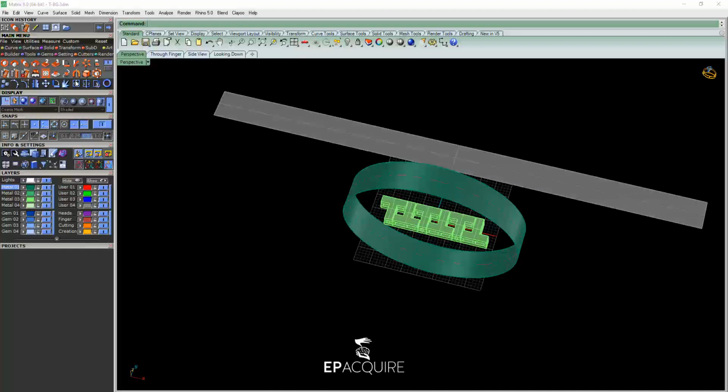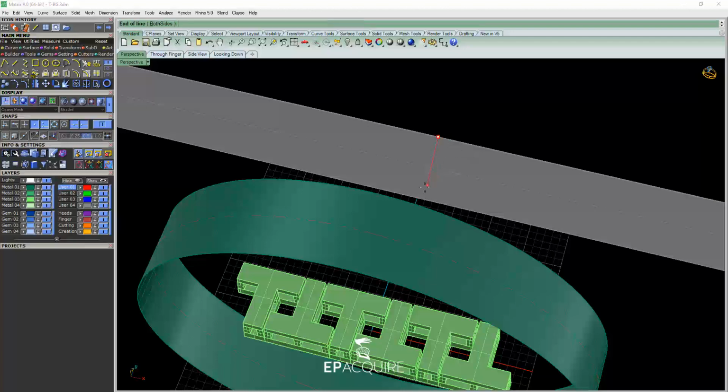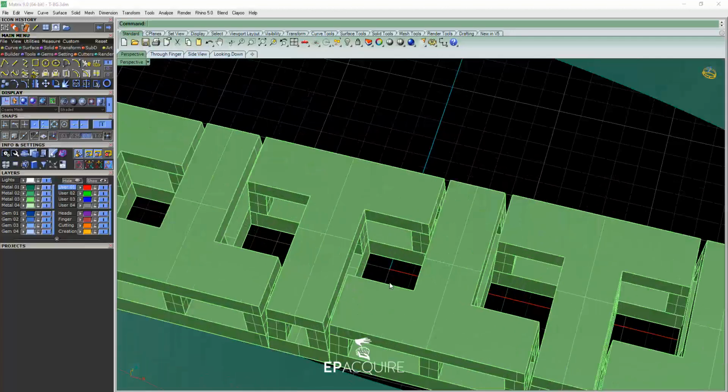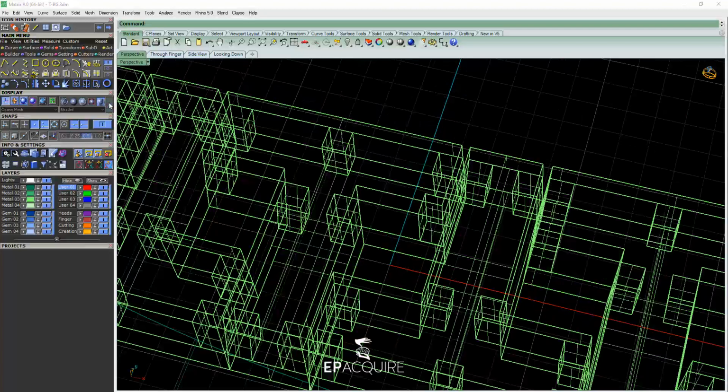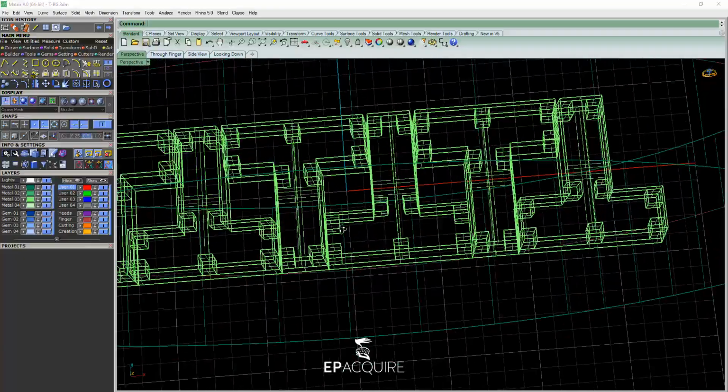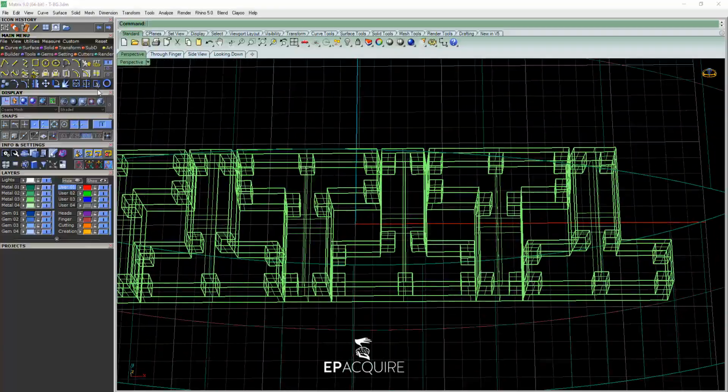Now what I like to do when it comes to SmartFlow is I like to get the dead center of something, particularly if I've got a pattern like this that I'm trying to flow onto it. So I'm going to grab a curve again. I'm going to switch across to my red layer color here and just draw from that midpoint there to there. And then I also want to just turn off my shade mode for the moment, just so that I can get in and select my duplicate edge.